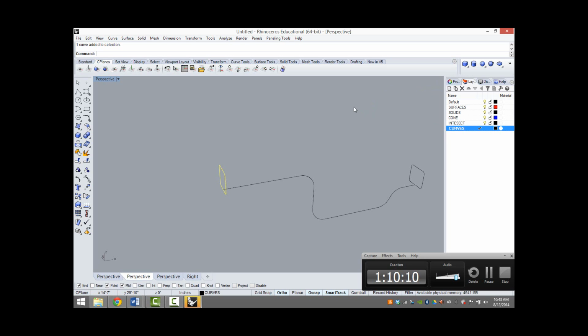Well, I haven't gotten into it enough to be precise with it, but I use it to push and pull things around the screen without editing the geometry. If you select an object with Gumball enabled down in this lower toolbar, it gives you options to rotate it in the X, Y, or Z direction, or move it, or scale.